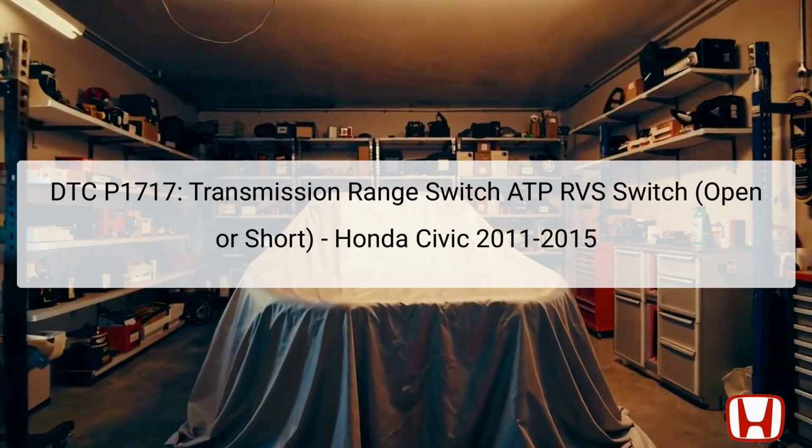The transmission range switch plays a critical role in the vehicle's transmission system as it communicates the position of the gear shift to the engine control unit, ECU. If there is a problem with the electrical circuit associated with this switch, it could lead to performance issues or prevent the vehicle from shifting correctly.